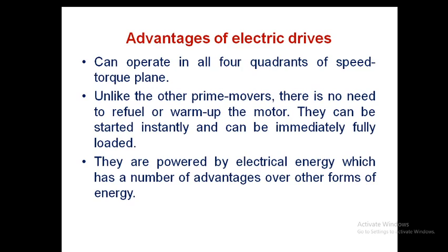This four-quadrant speed-torque plane is required in almost all applications. By using this electric drive, we get those four-quadrant speed-torque characteristics. Four quadrants means forward motoring, forward braking, reverse motoring, and reverse braking. These operations we get by using these electric drives.